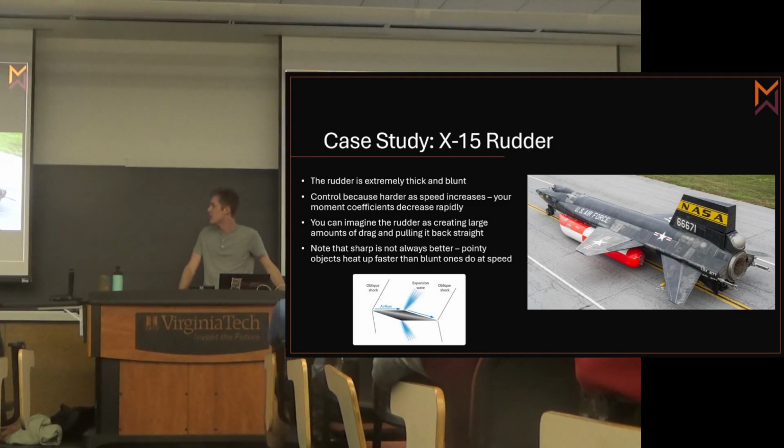Anything you want to add to controls? Yeah, I mean, it is funny. The rudder that they used in this one steered using flow separation off of it. So you steered it the wrong way to what you would think to get the aircraft to turn.